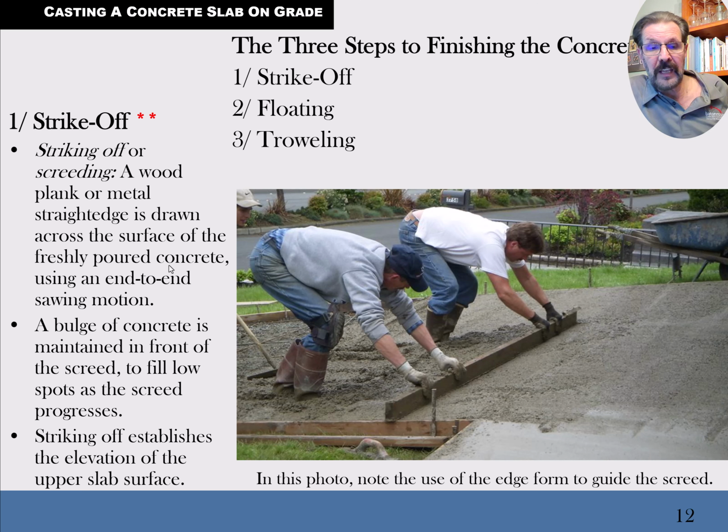And they don't always stand in the concrete. If it's long enough to go from side to side, they could be standing on each side outside of the concrete and screeding it across that way. And then you try to keep a little bit, not very much, but a little bit of concrete in front of it so that when you're striking it off, you're not creating pockets or depressions.